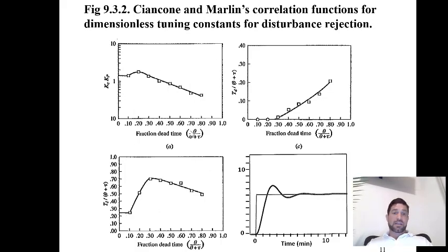Okay, so you can see here that my theta over tau, theta was about 3, tau was about 8, so about 3 over 11 was my fractional dead time. It's going to be somewhere around here. I can divide this value by my gain, which was about 12, and that gives me my Kc for that process. Again, in this case right here, same fractional dead time, it's about 0.2, 0.3-ish, somewhere around here. Tau I over theta plus tau. This time now, theta plus tau is about 11. So tau I divided by 11 equals about 0.6, 0.7.